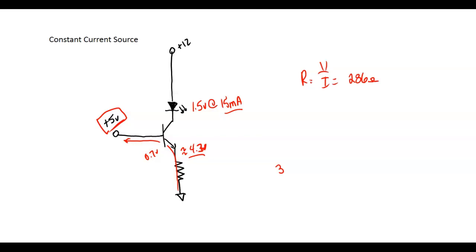So it's up to you. If I go up, the LED would be dimmer. If I go down, the LED would be brighter. So I decided to go down. So what size am I going to use? And then I chose the resistor that I had. No, I didn't have a 240. I don't have a 270. I got a 220. Now, if I had a 240, I would probably use a 240. If I had a 270, I'd probably use a 270. But I used what we have in our stock. So instead of 15 milliamps, it's going to be around 19 milliamps, which is okay.